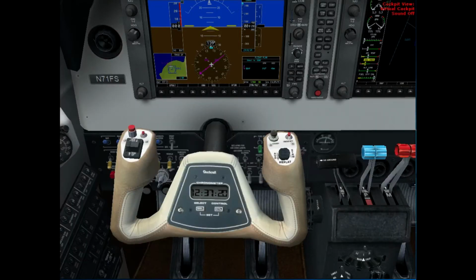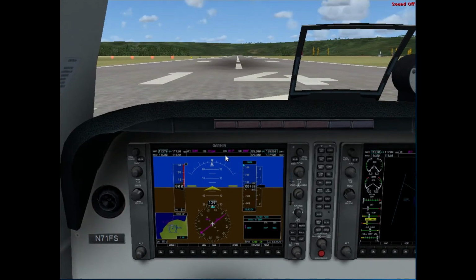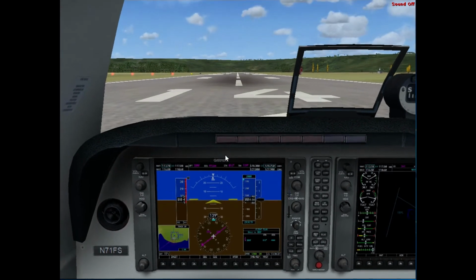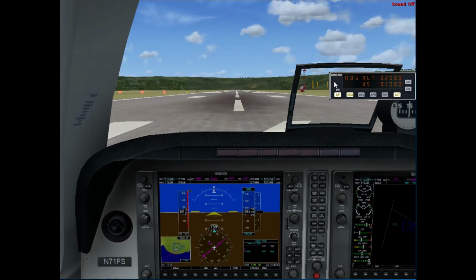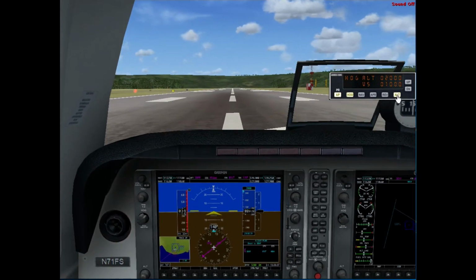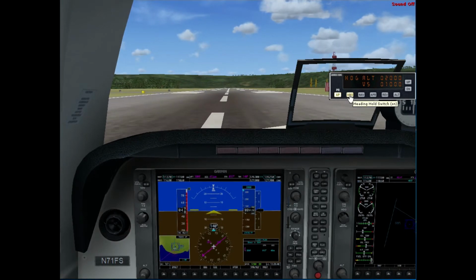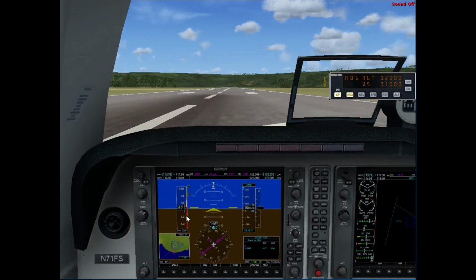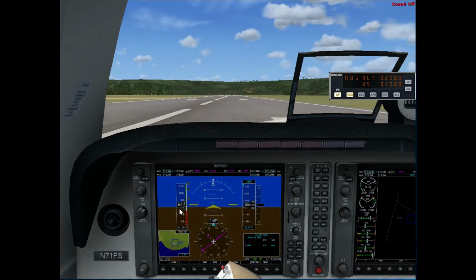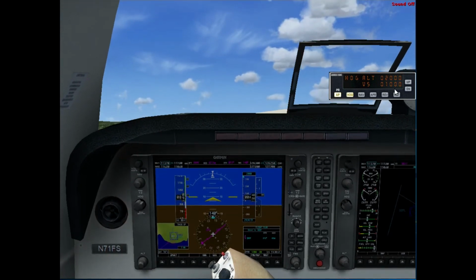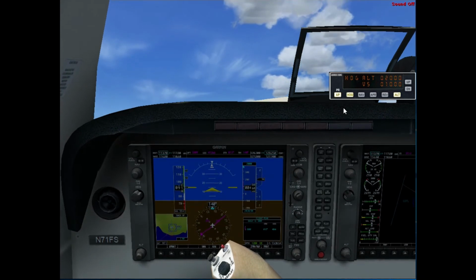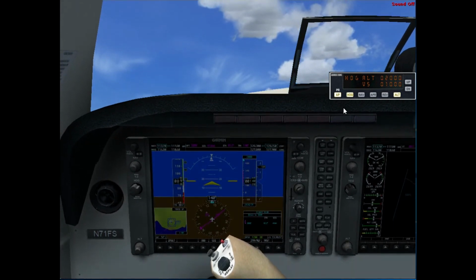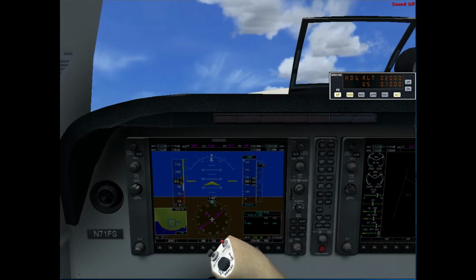I'm going to put the flaps, only one flap here, and I'm going to press F4 full power and leave this window open to set my autopilot. I will leave only the HDG on, and we have a look at the airspeed here. Altitude hold switch is going to hold our altitude. Gear up, we press G. Retract the flaps, F6.